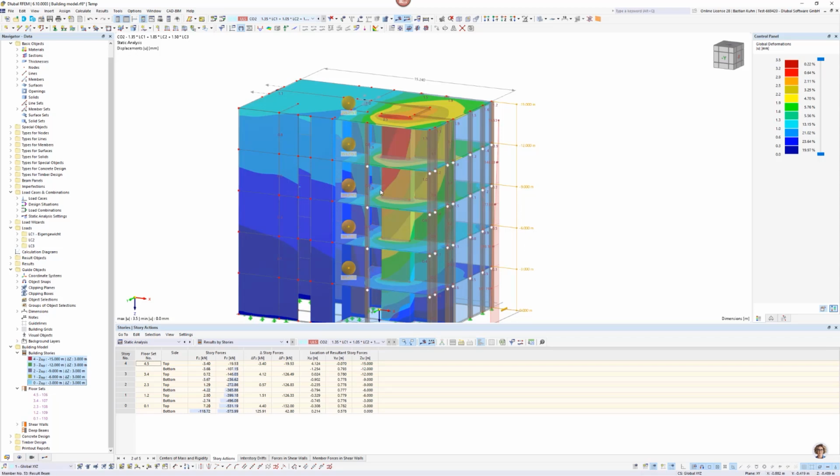The semi-rigid diaphragm is a function where you can also regard couplings either in concrete or CLT floors and decks. The stiffness center of the structure is different than the mass center, and the output of the either reinforced or not reinforced concrete or timber walls are possible via the design configurations.